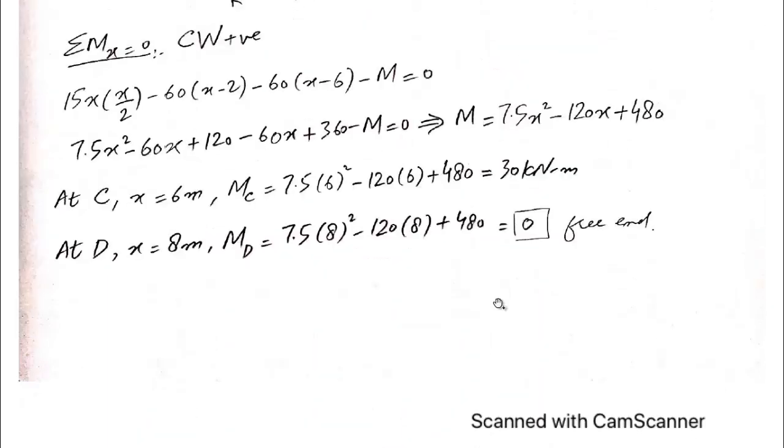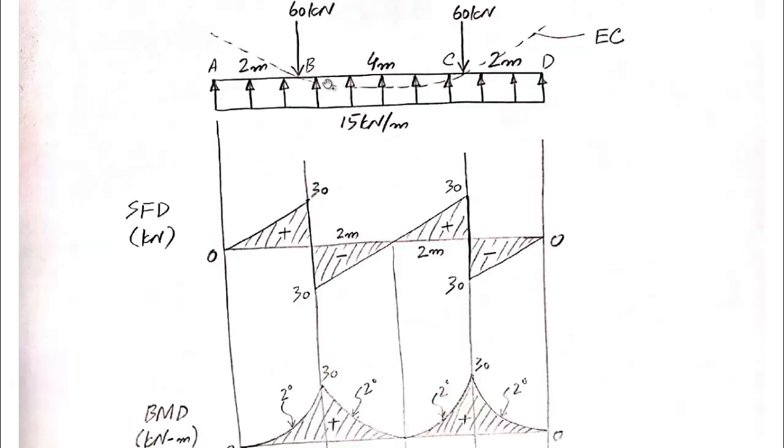So if we come to this diagram, I have to draw the elastic curve on the beam. This is the center line of the beam, and these are the point loads. We can assume these point loads just like the support reactions, and our elastic curve will pass through these points. The intermediate part of the beam will sag down, and for the remaining part we will just continue the same trend on both the sides, and this will complete the elastic curve for this diagram.